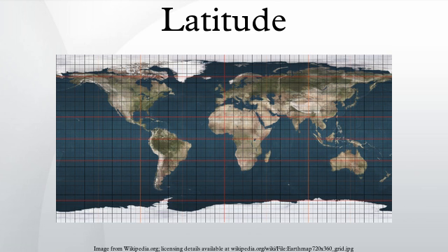The importance of specifying the reference datum may be illustrated by a simple example. On the reference ellipsoid for WGS 84, the center of the Eiffel Tower has a geodetic latitude of 48° 51′ 29″ N, or 48.8583° N, and longitude of 2° 17′ 40″ E, or 2.2944° E.